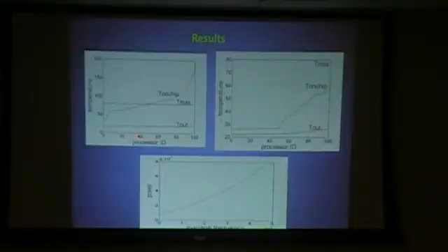And we set up a simulation environment, and we found that just because your air temperature is around 30-35 degrees Celsius, that doesn't necessarily mean that the temperature at silicon is within safe limits.